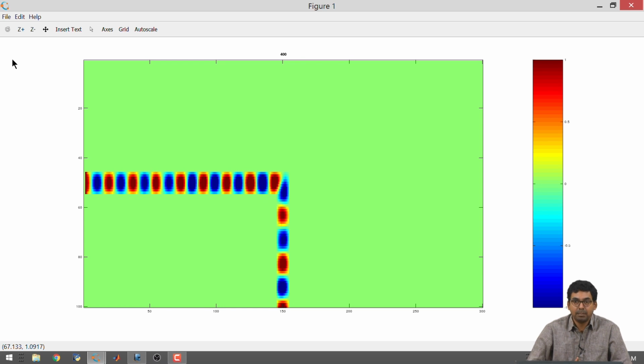But it is clear that the operating frequency, the size of the waveguides, the bend that you have, the size of the source, all of these are ways for us to excite and probably propagate different kinds of modes in your parallel plate waveguide. So, I think with this 90-degree thing, it should be clear that indeed you are seeing some waveguiding action.